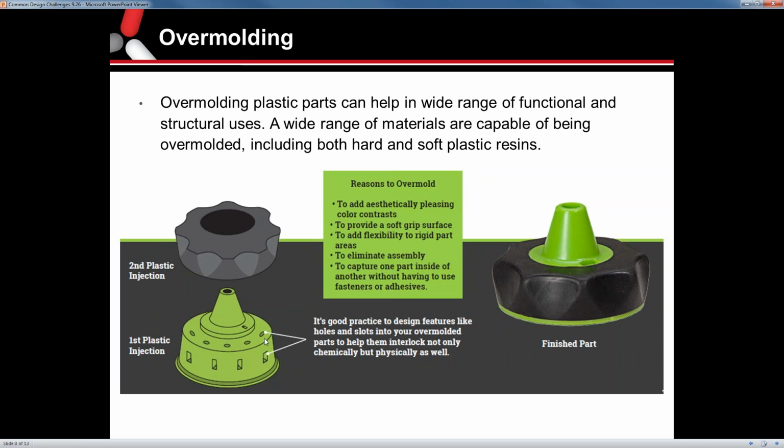There is a process called two-shot, where it's all done at the same time within the same mold, where the injection mold press is shooting two different materials. Substrate shoots, mold rotates 180 degrees, shoots the second shot while a new substrate's being shot. We don't do that here. We just do more of the manual process, since we deal with low volume. That's going to be more production, high volume type work. You're built in two molds. Right. Essentially. Yes. Hopefully that answered your question.